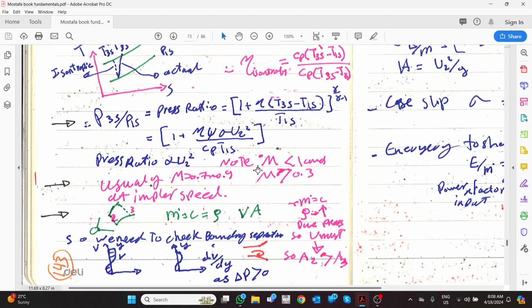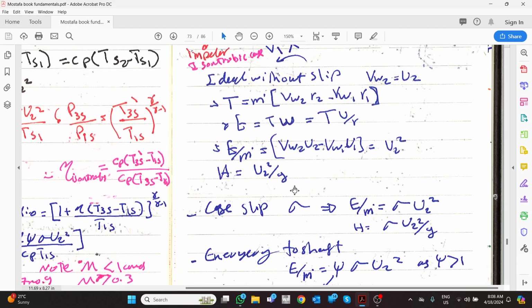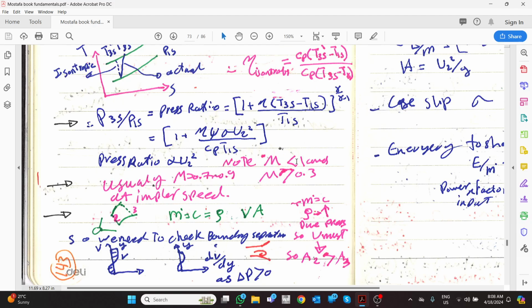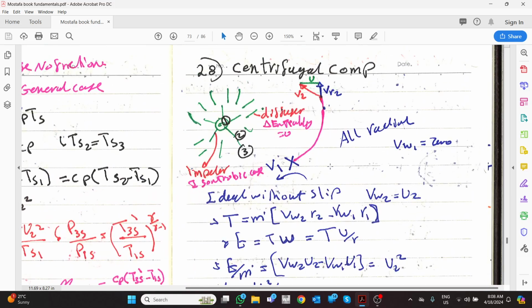Okay. Now, what is our approximation, or what is our understanding which you need to apply? You need to identify if you're doing a simulation or CFD. You need to check that you don't have a Mach number less than 0.3, because if you have a Mach number here less than 0.3, the fluid will not be compressible, so it will not work as a compressible fluid.